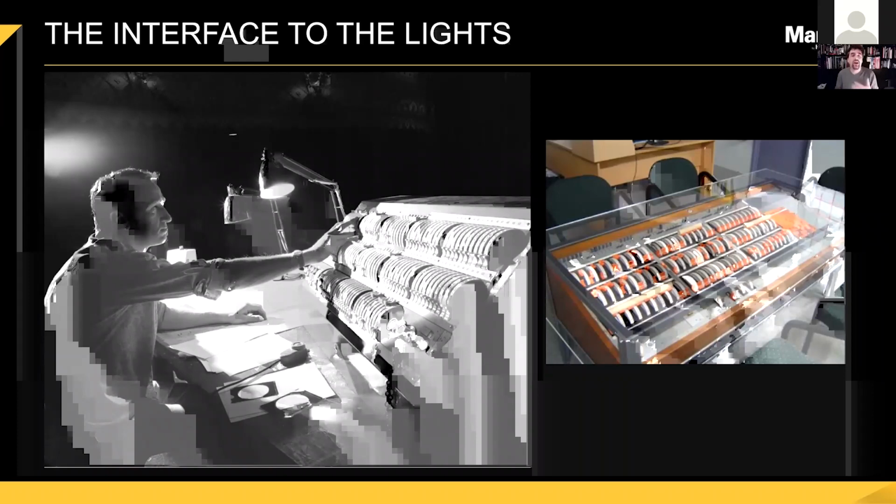And what you would now have the ability to do is to have multiple sets of faders per dimmer. So on bank 1, preset 1, preset is another word that gets reused over and over again in lighting. You could set Q1, have it live on stage. You could have Q2 preset, crossfade to Q2. Now you can clear bank 1, set Q3.